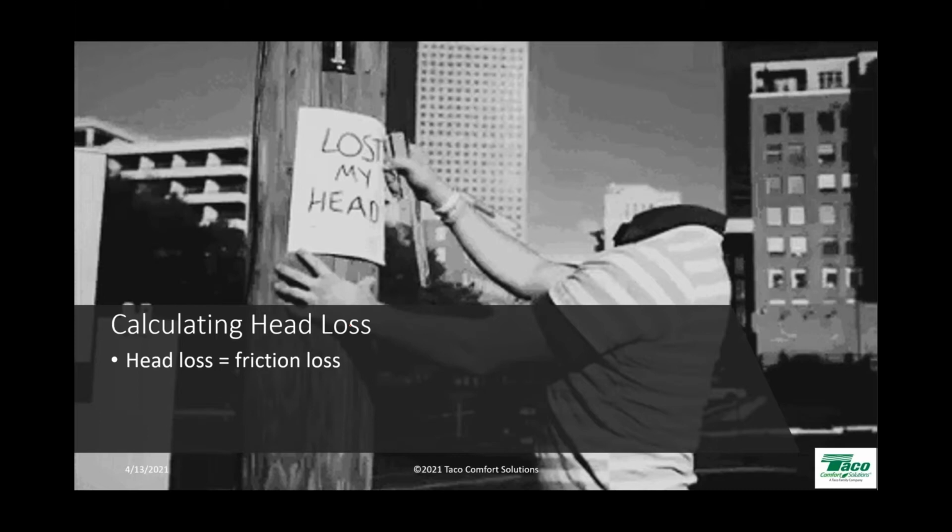Now we talk about head in feet of head, and too often people think feet of head equals feet of height. I got to pump that water up 3 flights of stairs, so it's got to go up to the 3rd floor. I got to figure the lift. No, you don't. It's a closed loop system.